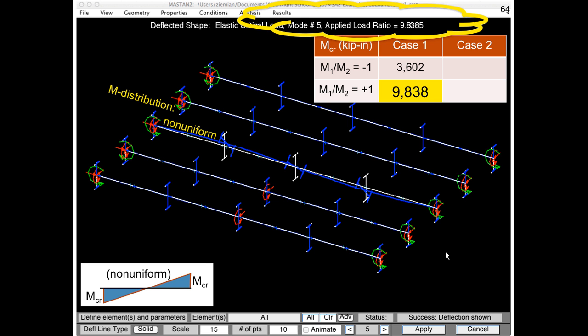If we start from the left end over here, we've got bending moment being applied so that the bottom flange is in compression. Somewhere along the span, and I just provided a couple of these dummy elements for you, you can see the bottom flange is buckling and twisting the section. The top flange is in tension, the bottom flange is in compression. It buckles and the section twists.